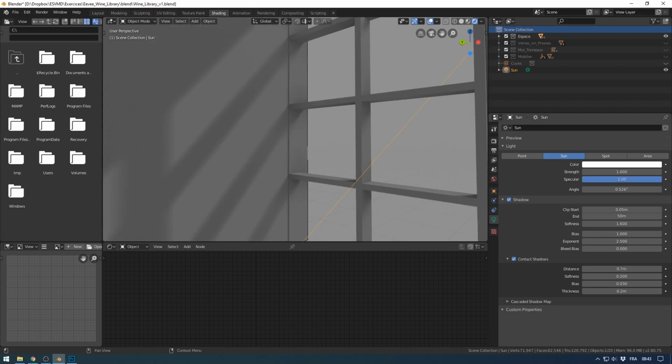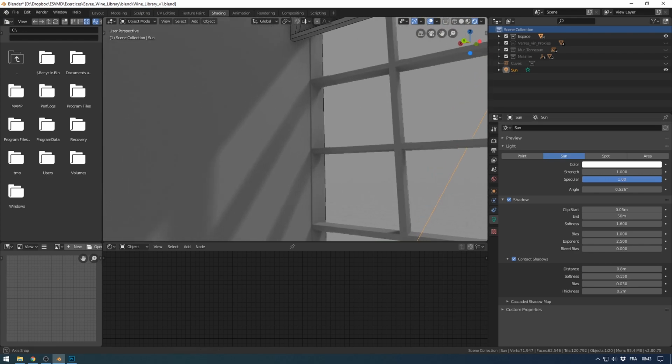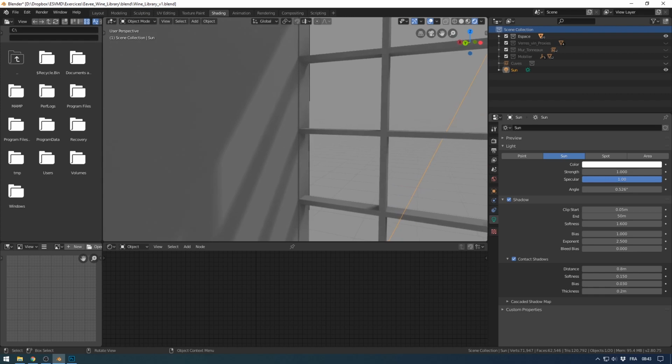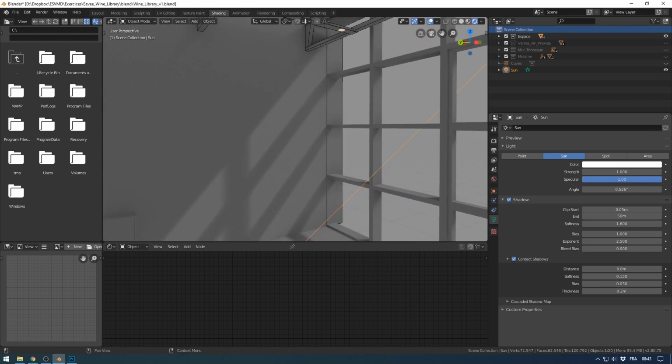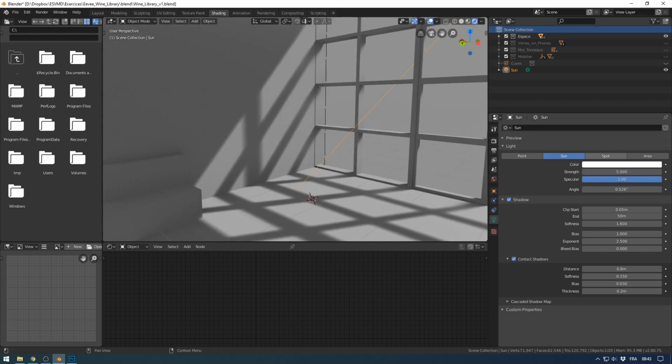And I could just blend here. Usually I like to blend the contact shadow with the shadow, so I use something like, in this case, 0.8, and the softness to, I think 0.15 is okay. Usually you would like to make the softness of the contact shadow similar to the softness of the shadow. So that's good. I will set the strength to 5, and the softness to 1.25 here, 1.4.